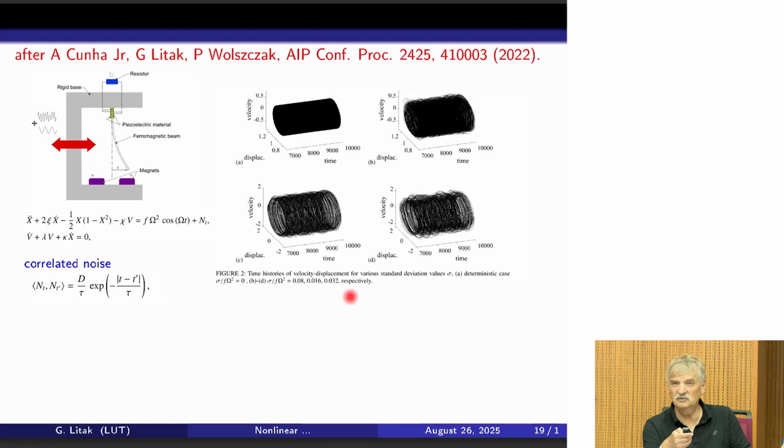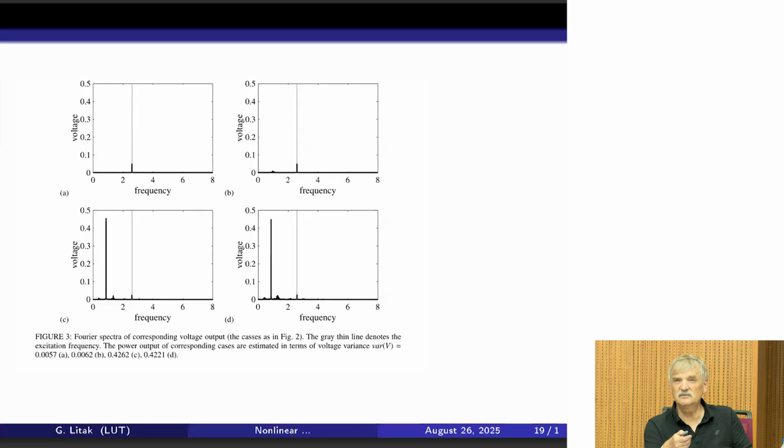So you can look, for example, at calculating the frequency and checking the leading frequency by Fourier transform. And then by Fourier transform, you see that if you have zero noise, the output is like a peak line, and there is another dashed line. The dashed line is the excitation frequency, and this is the response, the Fourier transform of the response.